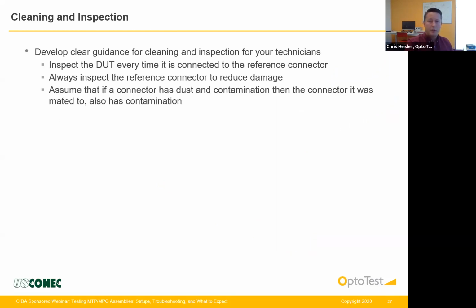Each DUT shouldn't only be cleaned every time, they should also be inspected. Cleaning an end face does not guarantee that all the contaminants were removed. To reduce damage to the reference connector, it should always be inspected. This connector influences the measurements on all connectors mated to it, and as such should be cleaned and contaminant-free. When a connector has contaminants, it is fair to assume that the connector it was mated to will also have contamination. When a dirty connector mates to another connector, typically the contaminants will transfer between connectors.